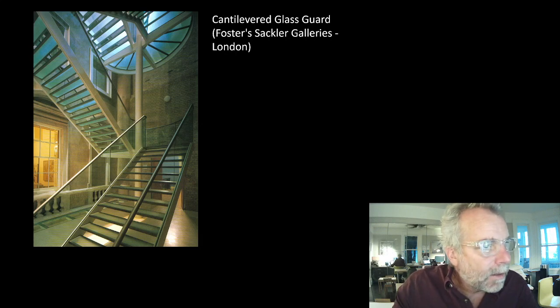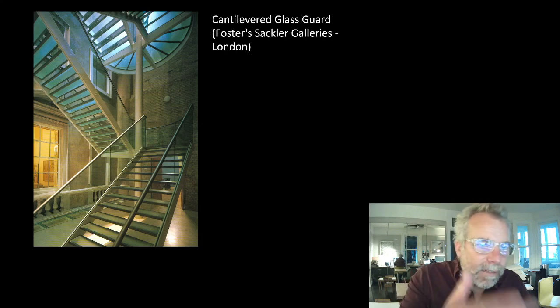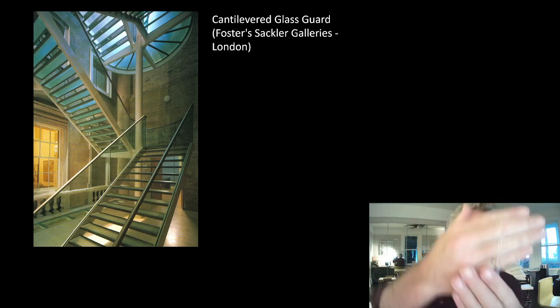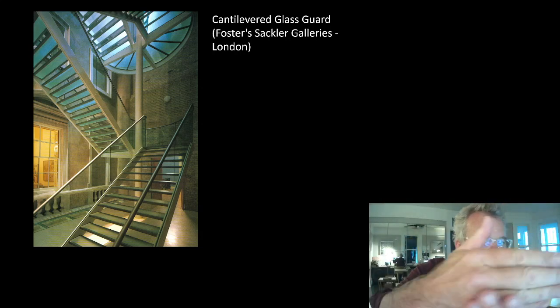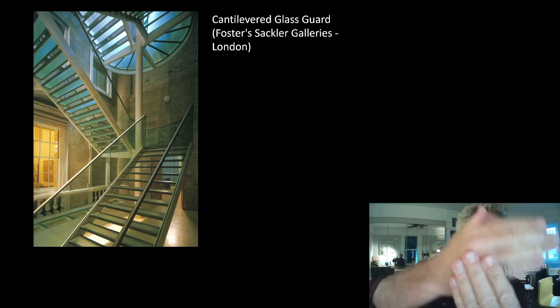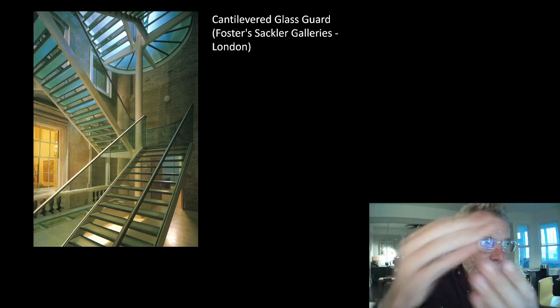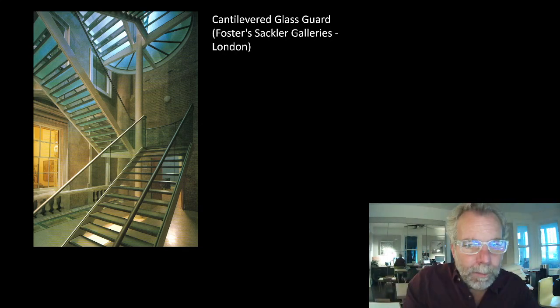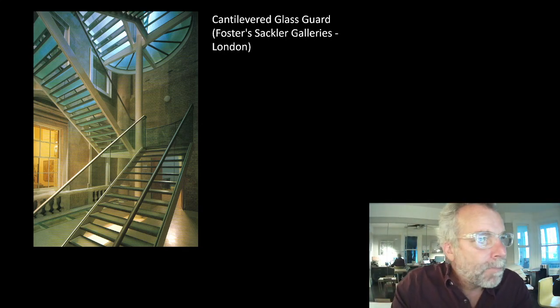Introducing glass handrails in a shoe introduces damping because the glass itself is effectively perfectly rigid. The steel stringer is not as rigid as the glass, which means that the steel stringer is trying to sag while the glass is trying to remain rigid, and the glass will slip within the shoe a little bit. And that slip creates friction that absorbs energy and gives us damping.